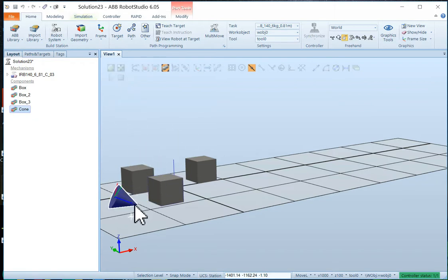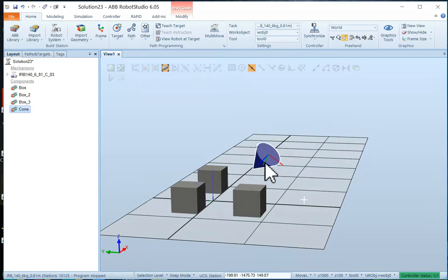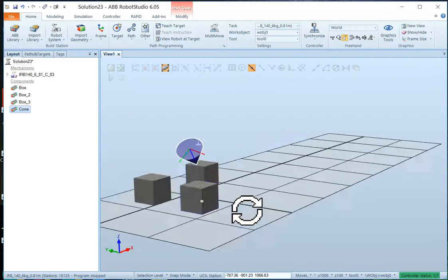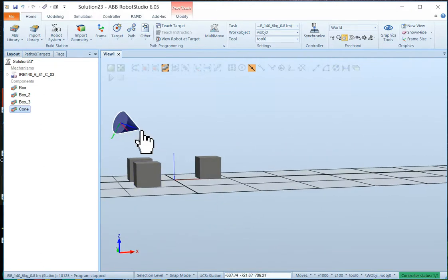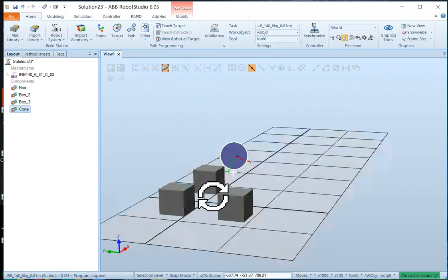Okay, I'm going to turn off the simulation so the cone should behave a little bit better. Let's see where it is now. Oops, simulation off, please. Okay, that little green line has gone away over simulation, so it's now off. And let's see if I can drag it over top of the box. You can try this too on yours. Okay, and it's right over top.